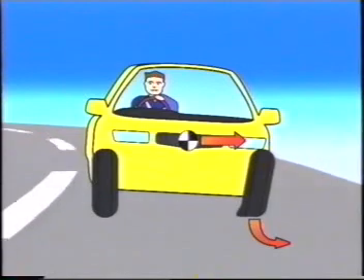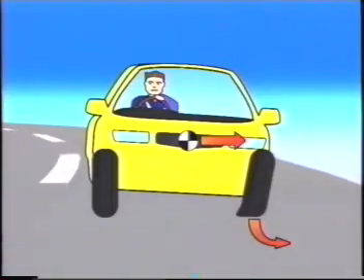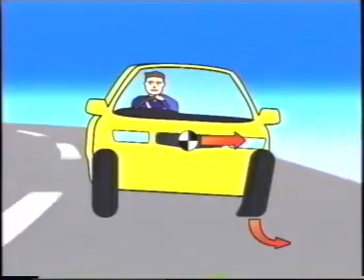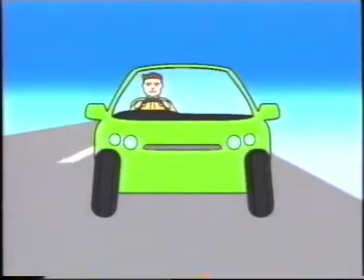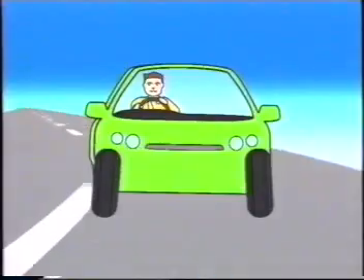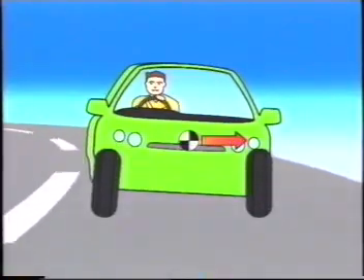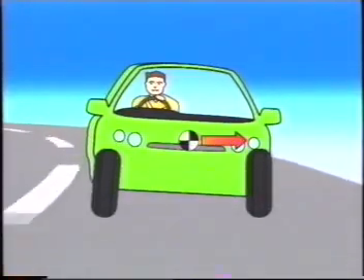When this happens, a heavy load is applied to the tires on the outside of the turn due to the centrifugal force. Then, as you can see from the previous experiment, camber thrust acts on the outside tires in the opposite direction to that of the turn, degrading cornering performance. So the aim of giving the wheels negative camber is to ensure that the tires grip the road surface properly, even while cornering, improving cornering performance.